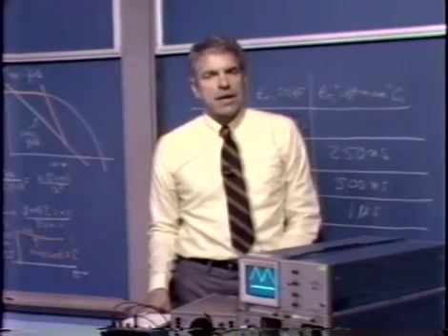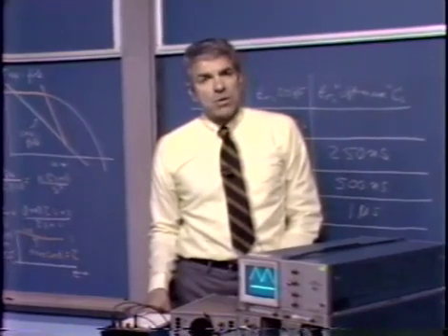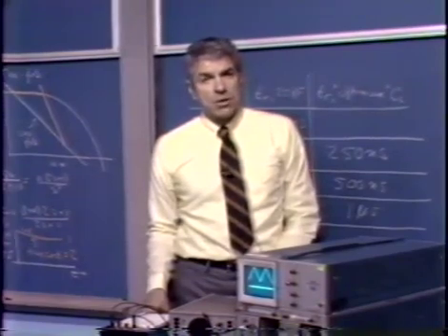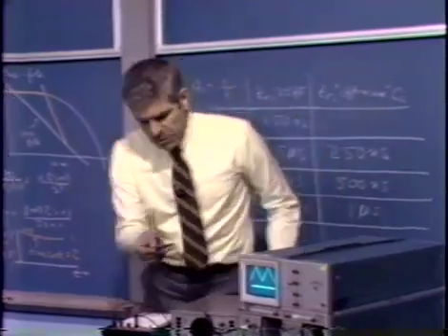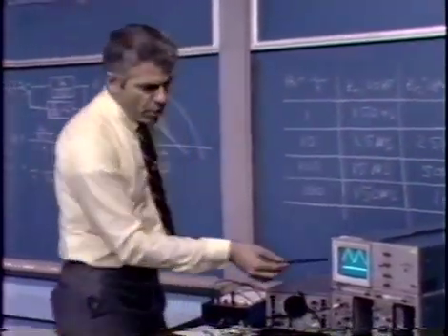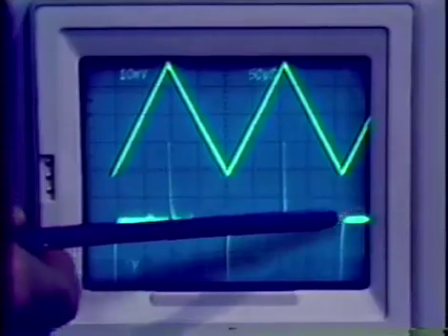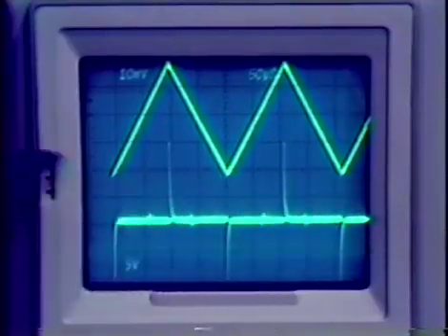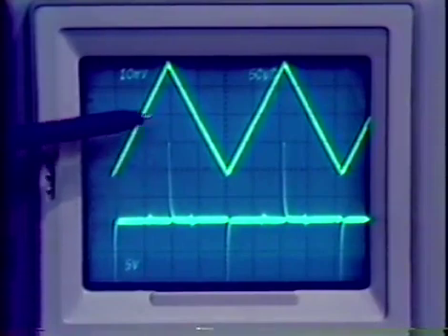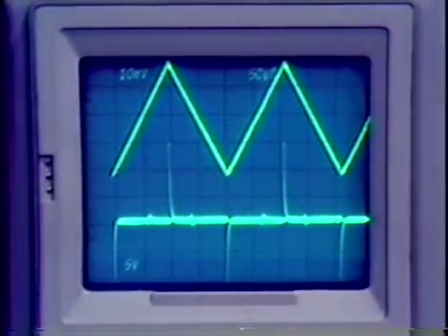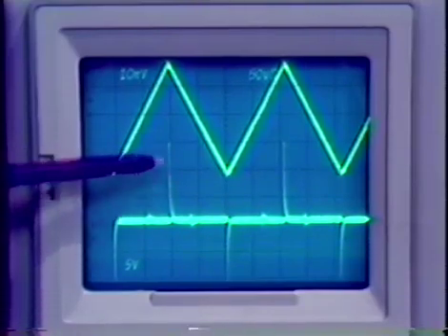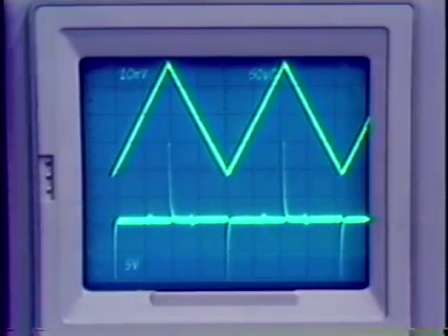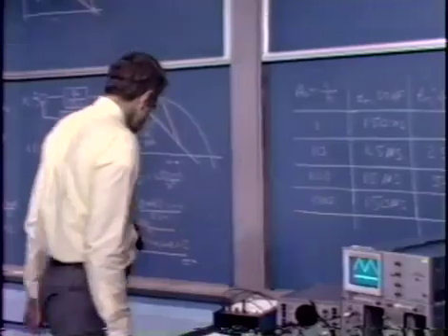They don't go to infinity and all that, reflecting the fact that we don't have a 1 over S squared transfer function at all frequencies. But we get a series of small impulses. And the important point is that most of the time, the error is much, much lower for 1 over S squared compensation than it is for 1 over S compensation. That simply reflects the fact that the open loop transfer function with 1 over S squared compensation is much, much larger at many, many frequencies.